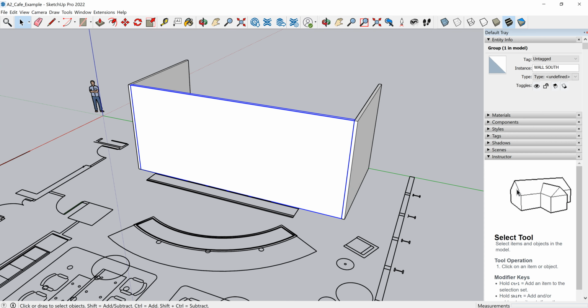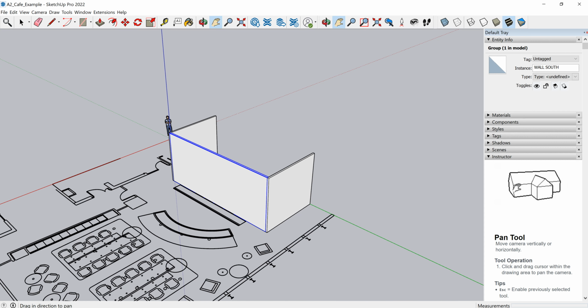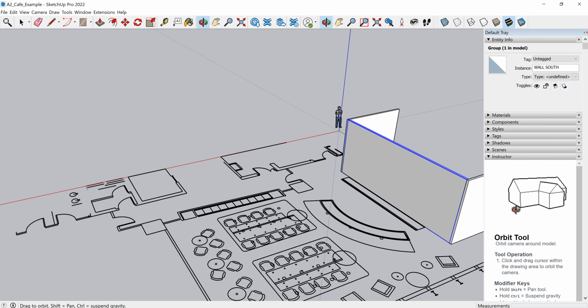So for every wall that you create, literally in here, some are at an angle, some are straight, you are going to want to group them. So you kind of want to get in this habit in SketchUp of you build, you create a group. You build, you create a group, and you name it properly so you can find it at any time, and it just saves you a ton of time later with this stickiness, which I'm hoping to show you in this little video.